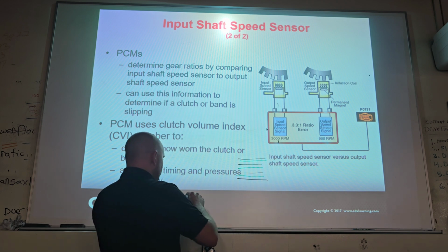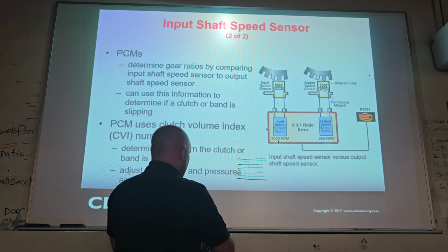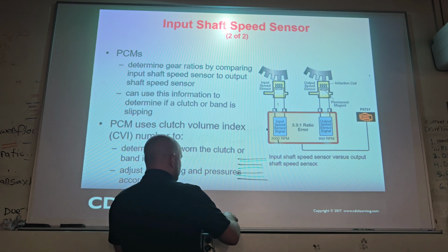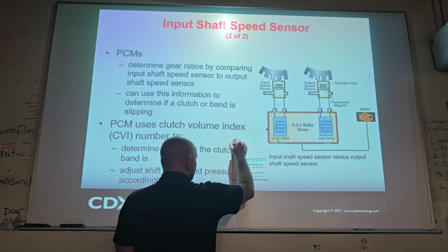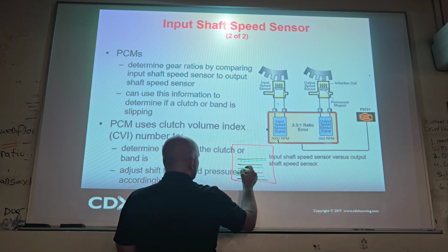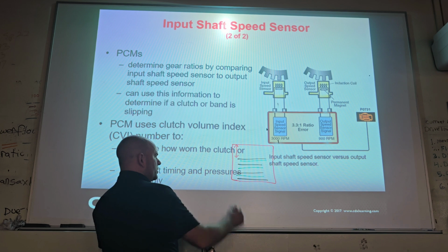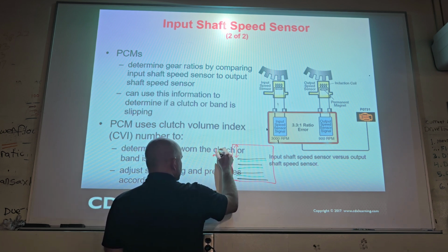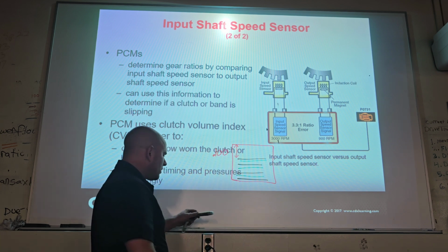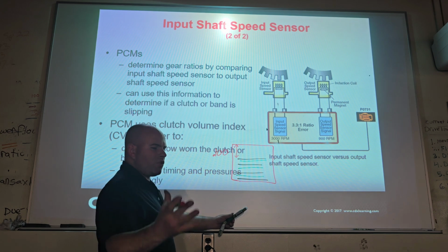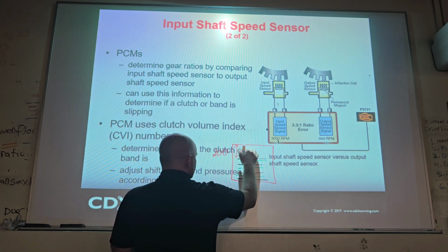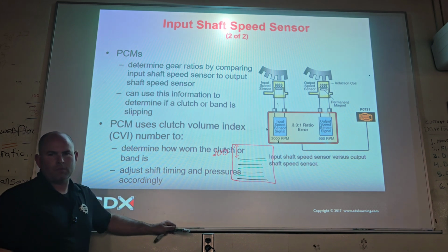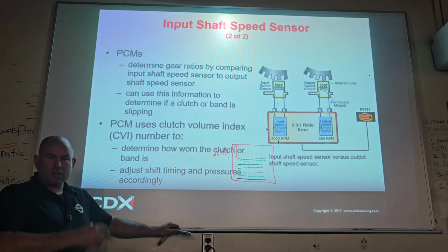Clutches and steels, right? And then in the bore, in the housing, this has got a certain amount that it can move in the actual piston bore. And if you look right here, that's how much movement it has. And let's just say it's a 100 thousandths. Cool. When we send fluid to that piston, it's got to lift these clutches and squeeze them. How much did it have to lift them? We measured the clearance right there, right?